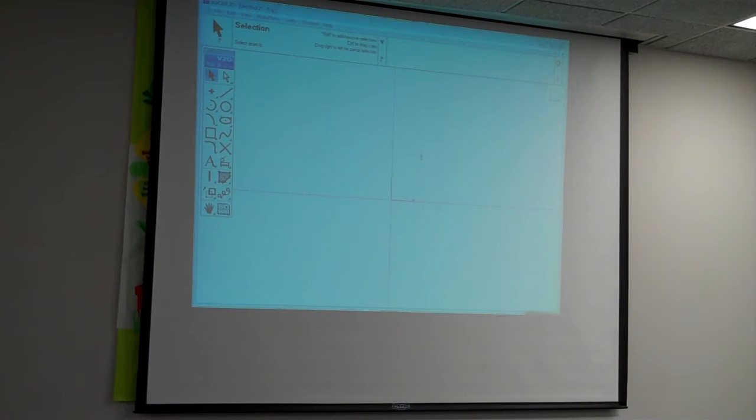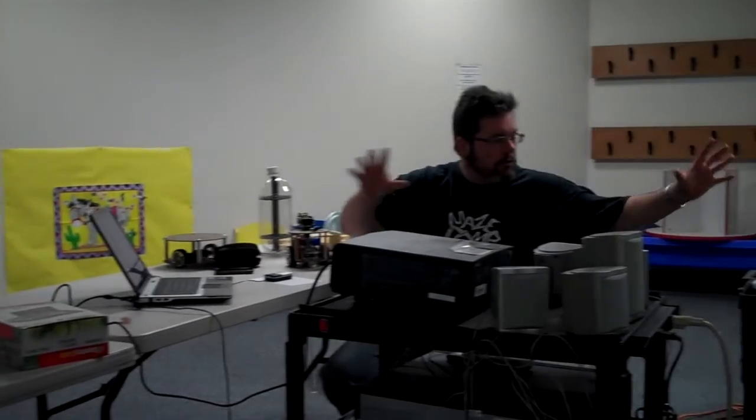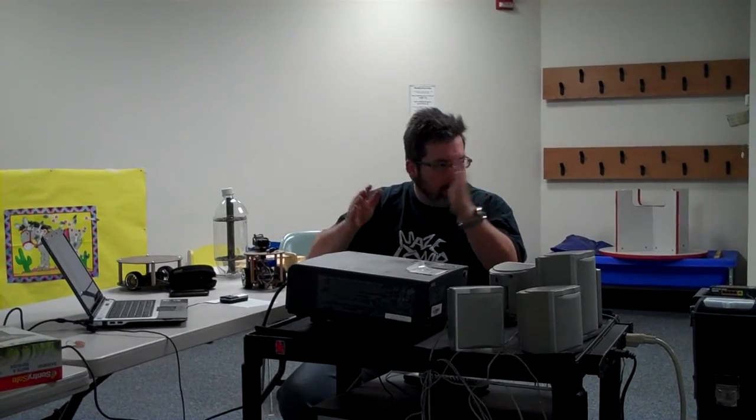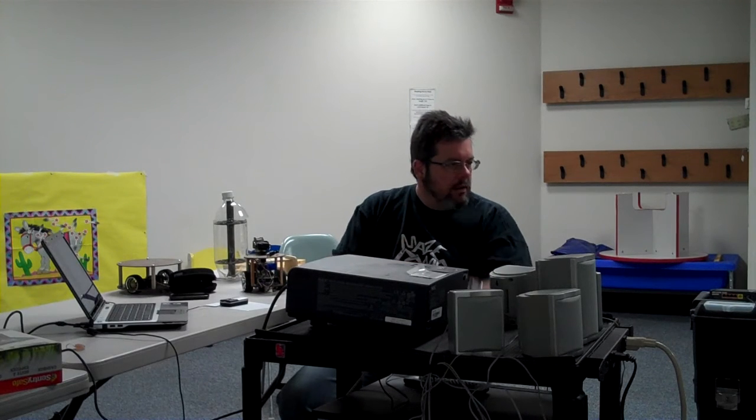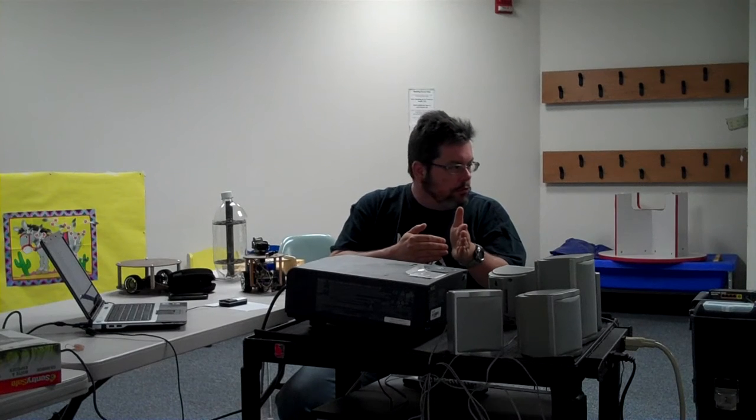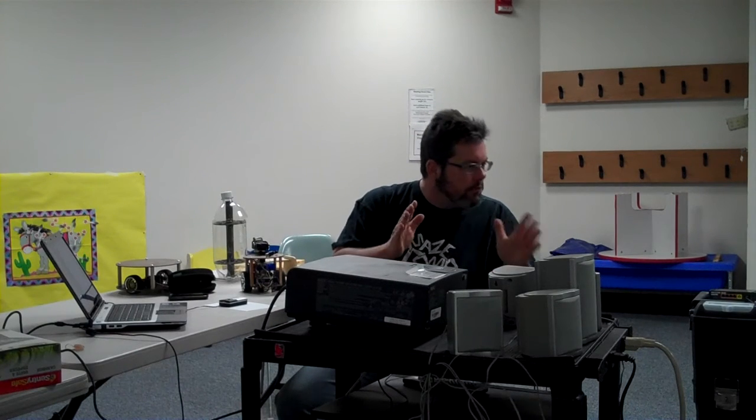That kind of lets me know I need to stay in this quadrant up here. So if I'm drawing something, or maybe I draw something that's bigger but then shift it over, I got to be about 1/8 of an inch inside of these lines. Otherwise my machine, for safety reasons, will say you're attempting to move the tool beyond the limits and it'll just stop. Okay? So we've got that quadrant built there.